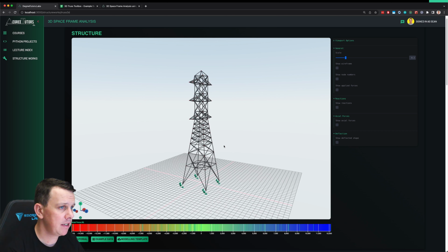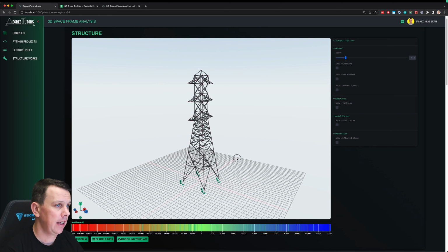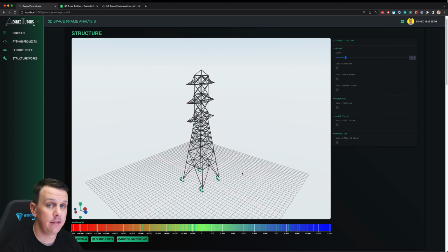But it's handy. In particular, I have in mind students doing projects. You just want a quick frame solver, and you want a nice way of generating some interesting models, and then getting a force distribution for those models, some deflections. I see a lot of students jumping into ANSYS and doing finite element modeling, which is the wrong kind of modeling to do for this kind of structure anyway. This is a nice handy tool for you to use, and so that's what it's there for. So go ahead and feel free to use it.